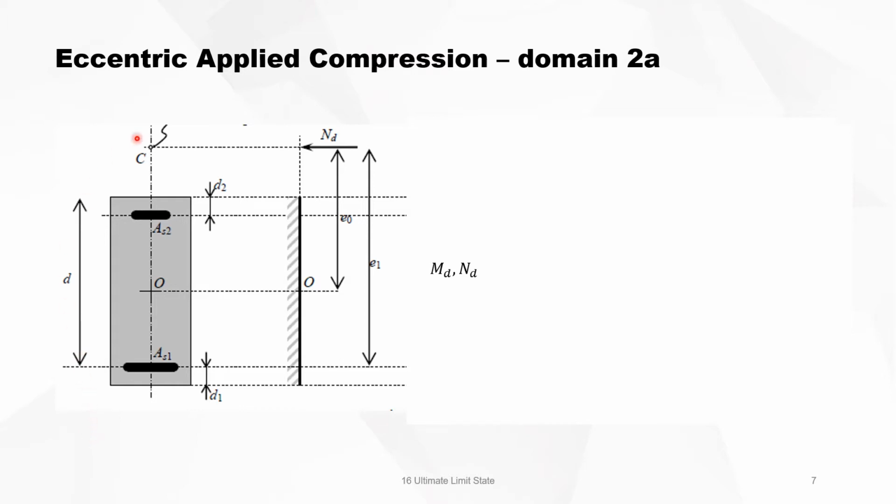It is always the same principle. At the bottom it's tension reinforcement, at the top compression. If the whole section is in tension, then the bottom is always the most tension side. And when the whole section is in compression, then the bottom is the least compressed side. It's just a convention to make it easy to make a drawing.